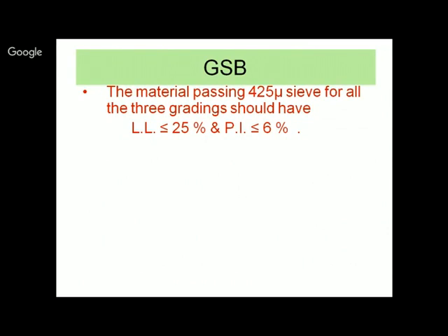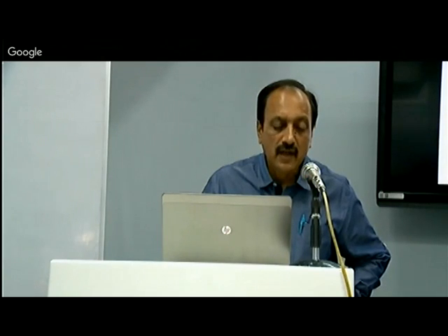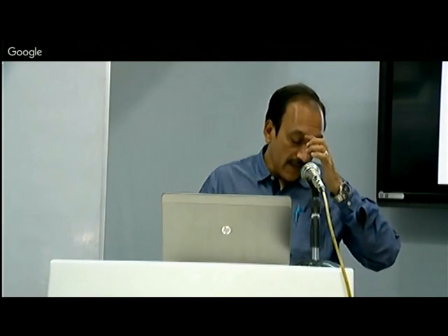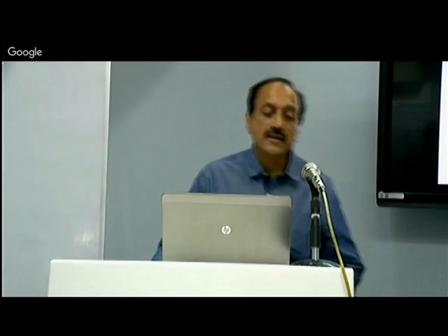Now then somebody could ask, why do I then have the finer material at all? 425 micron, what is the necessity of having finer material? Can I do without it? Well, you could do without it, if it was available like that in nature, but it is not available like that. Secondly, we said that the density will increase if you have the finer portion, because they will fill in the voids, resulting in denser material, and the denser material is going to be more stable.